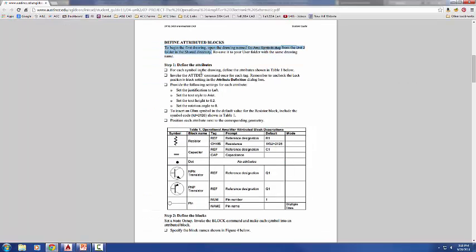Okay, so I'm going to show you how to set up each viewport to only show the layers that you want to see within that viewport. You've already created your own layer states, and you can find layer states on that Home tab. When you pull this down, these are the layer states that we've created. We're going to use these layer states, but a glitch in 2012 is that when I'm in a viewport, I cannot select the layer state from this list.